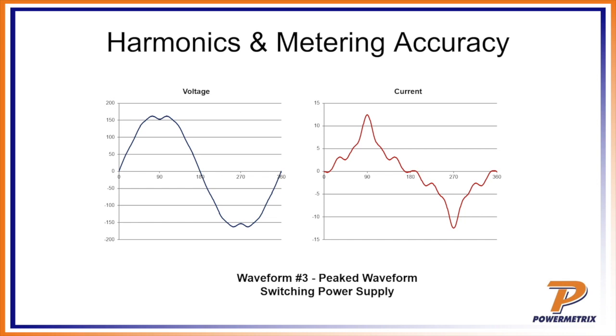You see the voltage is mostly sinusoidal. You'll see a little bit of an inflection in the peak and the trough, which, if you overlaid those two waveforms, would correspond to that big current peak that you see there. Basically, it tries to draw a big slug of current. The transformer responds with a little dip on the voltage, and so you've got harmonics being produced on both sides.